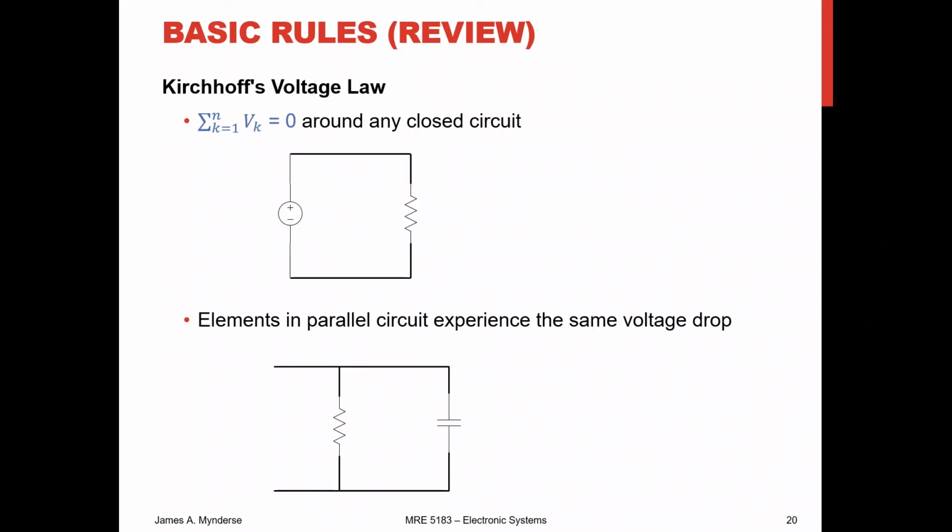We can do the same sort of thing with a voltage law. We know that Kirchhoff tells us as we go around the closed circuit, the sum of the voltage drops is going to be 0. And I do point out this is voltage drops across elements. Sometimes I see students that are confused. It's the drop across the element. So we've got, for instance, a drop across the supply and a drop across the resistor.